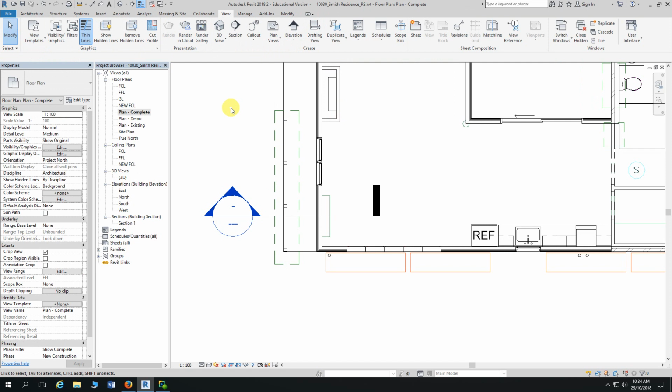So we've lifted the cut plane up very high, very close to the top of these posts. So at a cut plane of 1200, for some reason it doesn't work. It doesn't cut through these posts and show us them in section. If we lift it a bit higher, we could even go a bit lower than 2200 and it would still work.